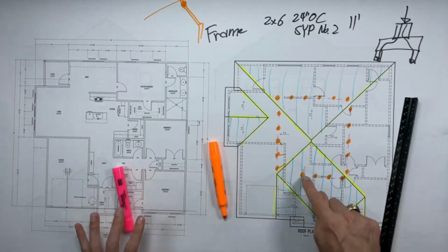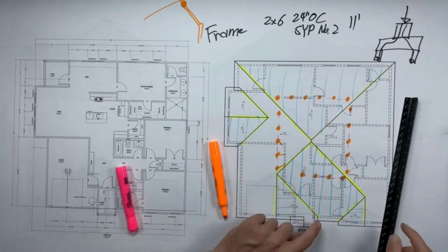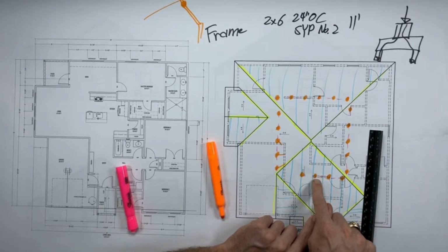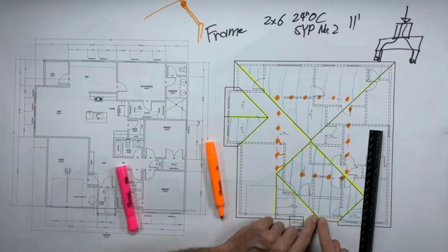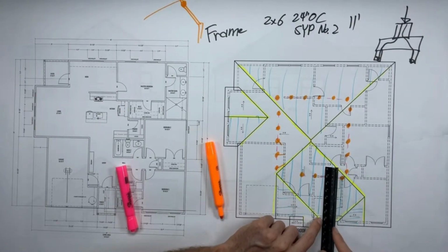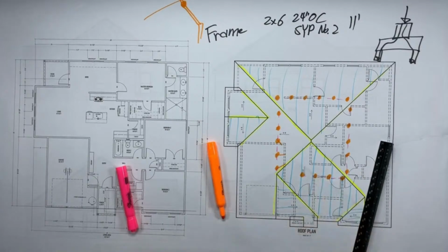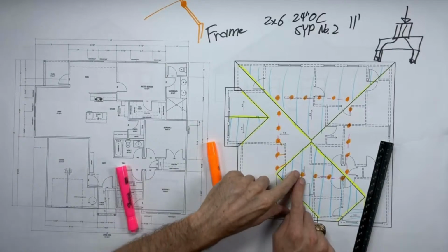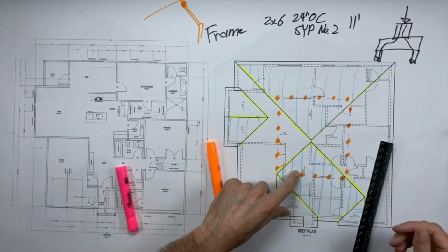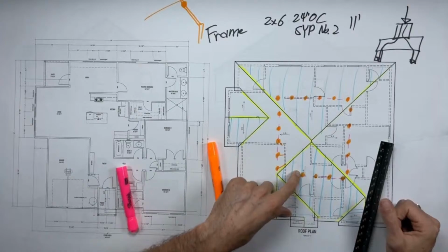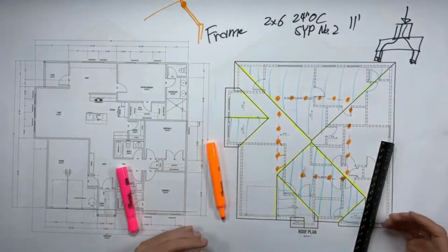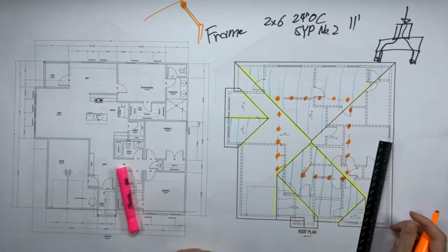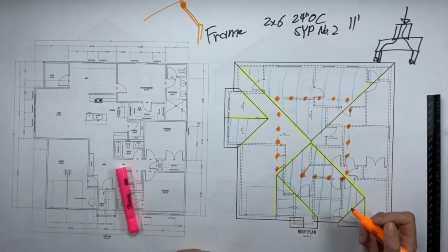So how do we know how high we are right here above 10 feet? Well, we'll start here at 0, and we'll find out how high up the roof we're going. Okay, so we're going up to this line, and these are all at the same height. And that distance is, well, it's a little bit less than 12 feet because we are approaching the 11-foot maximum. So since we're a little under 12 feet and our pitch is 8/12, let's assume we have, like, I don't know, 7 feet we could go, or 6 feet if we're being conservative. Basically, this roof is pretty steep, which means we have a lot of attic space, which means we have a lot of room to reach our braces. So we are certainly going to reach here because that's only about 4 feet. So that's good.